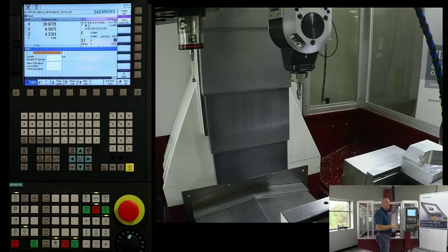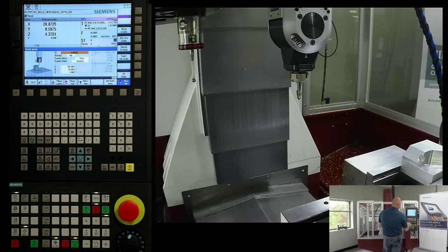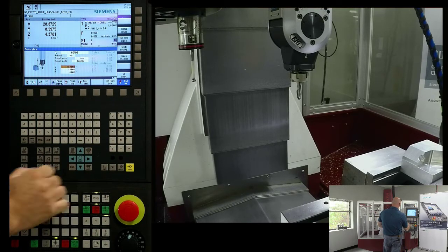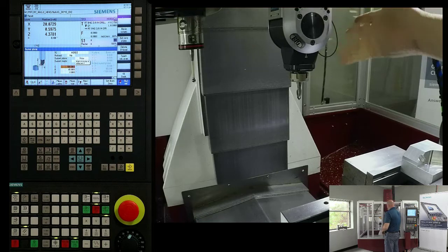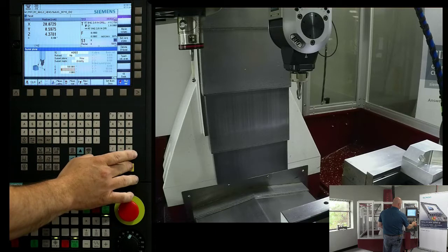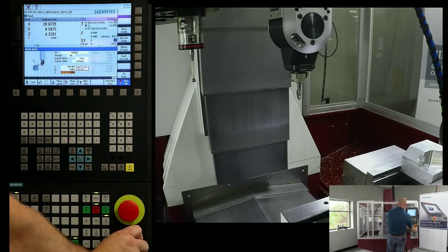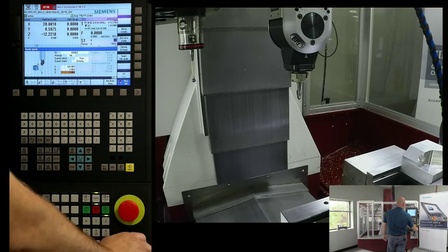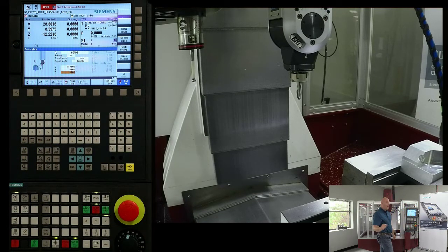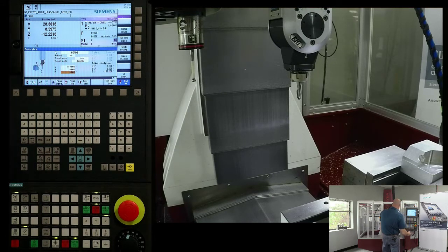Now from here, I do have to make sure I'm activating the swivel cycle because it's going to take those values into account. So go into Swivel and tell Swivel how we're orientated. I'm still sitting at 180. I didn't spin around. It really doesn't matter for the vertical orientation. But I need to tell it my B is at 0. So I go to 0, hit cycle start. The machine is now going to tell me to move the axes to 0. I hit cycle start again. And now I've established this orientation.